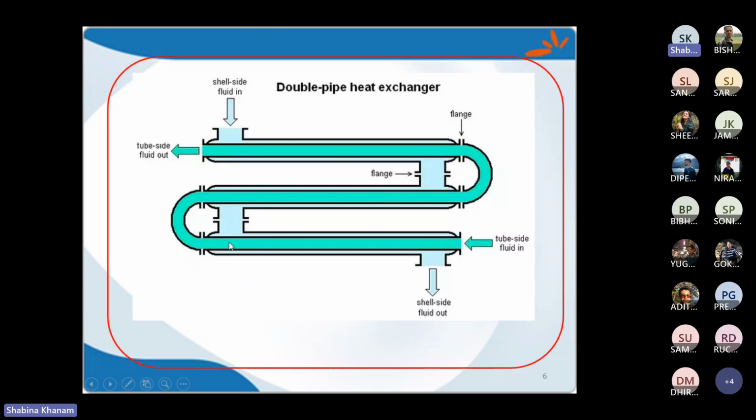So when we see this double pipe heat exchanger, after this it will be bended. The bending will occur over here, and then we will have the straight pipe again, where the heat exchange will be involved. Now the point is, this is the bend, right? And bending is done only in the inner pipe, not the whole shell and tube heat exchanger. The shell side, this outer pipe, ended over here and then it starts from here. But this bend is only done with the inner pipe.